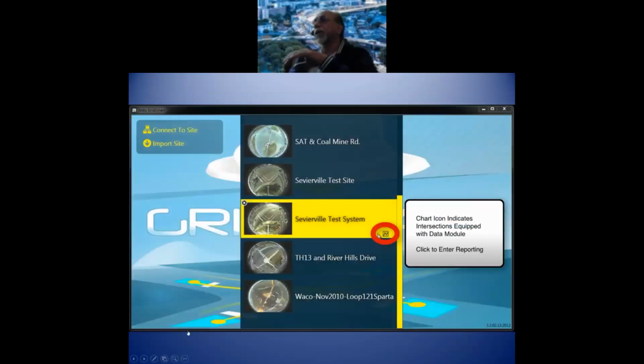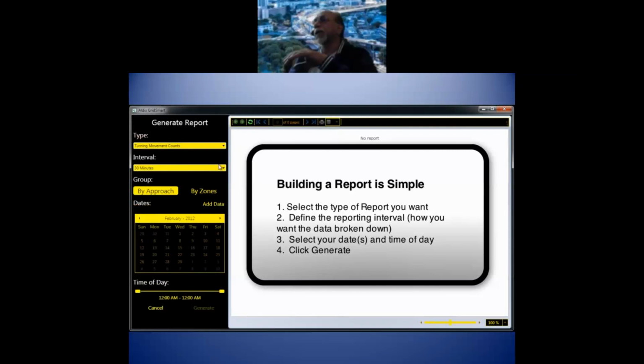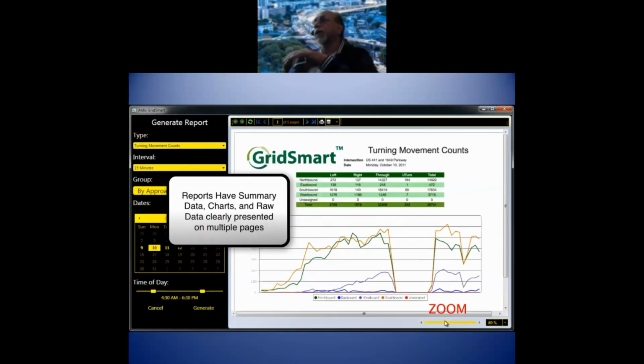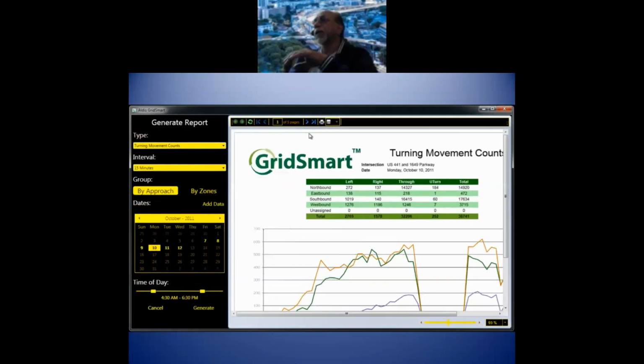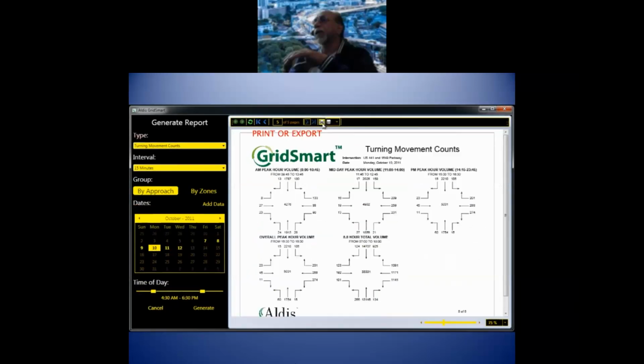You select the system. This is a 1 minute video. You want to build a report. You see what you want. You want turning movement counts. All right, 15 minutes interval. Then which is the date you want? Pick up the date. And then what time to what time you need? Pick up the time. Then you simply say generate. The moment you say that, it renders a report, gives it to you, and gives you the classification of the vehicles, northbound, southbound, turning movement counts, everything.